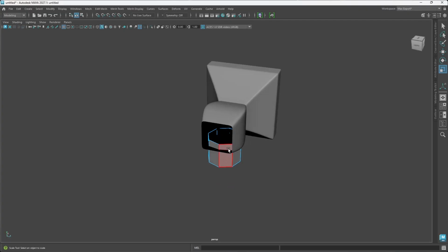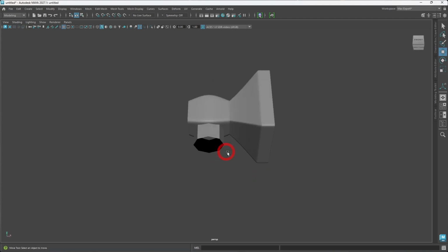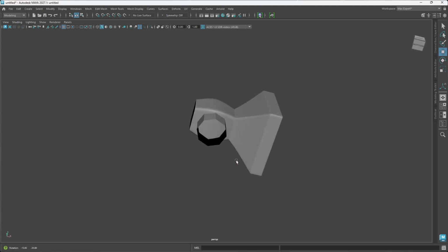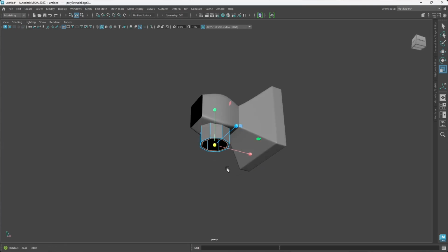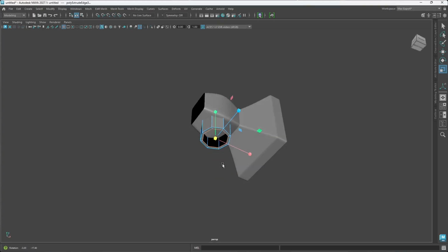Now, deleting the face inside does not really matter, but it is always good to just delete the faces inside since it's not going to be seen while making use of it. So let's go back into the object mode. So what we are going to do now is to add a little bit of a closing inside here. So we'll go into the edge mode, double click to select the loop round, hit on R, hold shift, and we're going to do smart extrude just a little, maybe, yeah, that is fine.